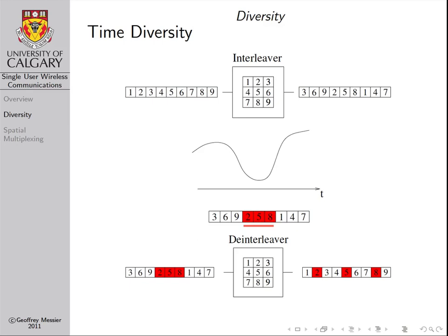However, you can't have the frames too long, because the disadvantage of the interleaver and de-interleaver structures is that it introduces delay into our communication system. The interleaver structure cannot start outputting its first bit until the matrix is fully loaded. And so there's basically a delay equal to 1 frame time to load the interleaver, and a delay equal to 1 frame time to load the de-interleaver, and that can cause a bit of latency in the communication link.